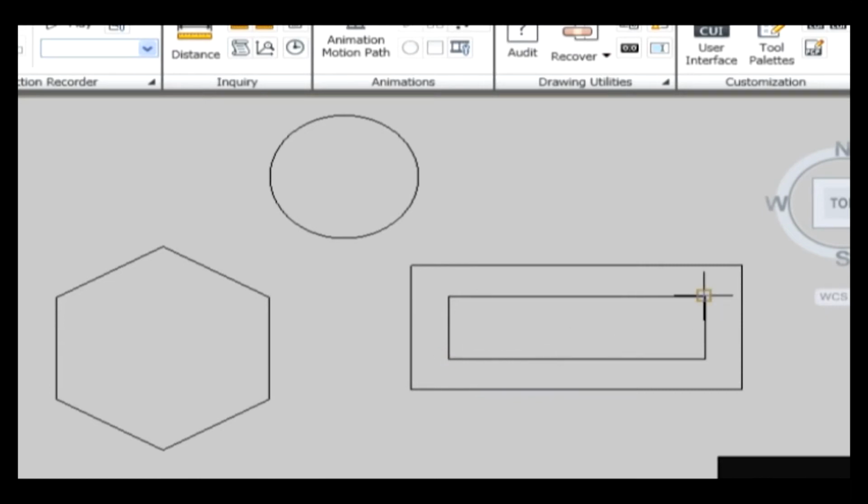Click on next corner of the object shown in the drawing area. Like this, we can select all corners of the object. Finally, press Enter to finish the selection of the point. Now you can see the area and perimeter between the selected points in command line. Let us see the sub-option Object in Area command. Object.